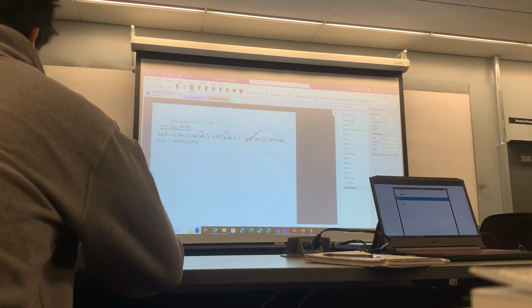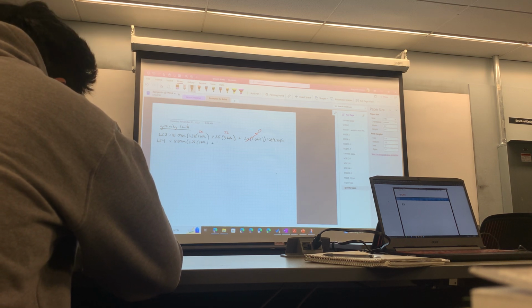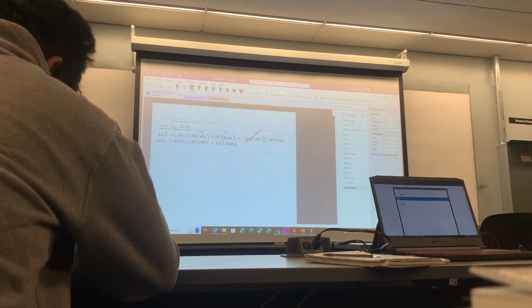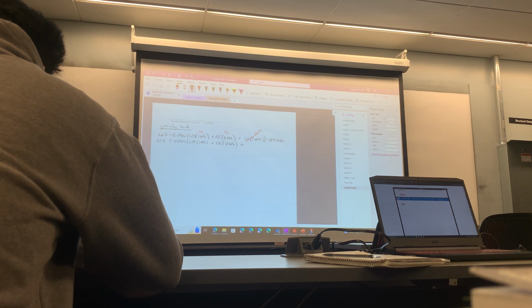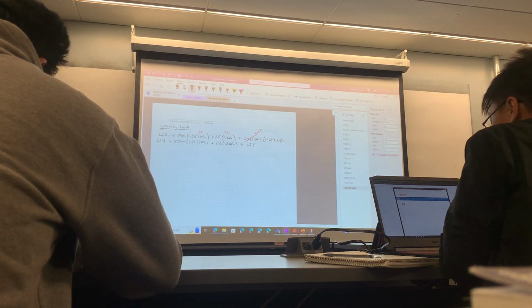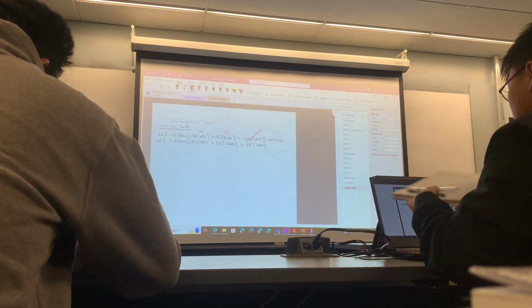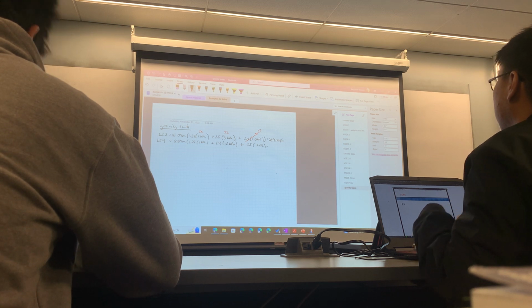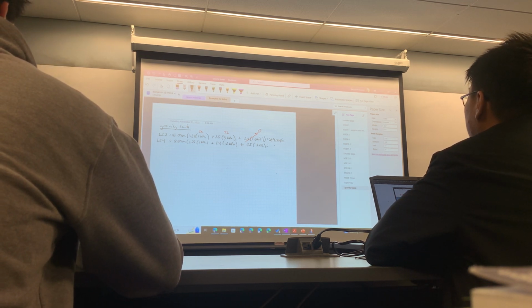We still have 1.25 dead, and this time we have 1.4 wind. We're going to assume the wind load is 0 on the roof. You know there's uplift and stuff like that, but for now we're just going to call it 0. And then we're going to have 0.5 snow, and that is going to be 13.83.